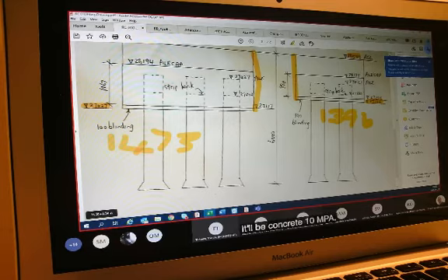One is blinding, and the other one would be my reinforced concrete. So it will be 10 MPa concrete, and whatever the size stone is that we will have, whether it be 19 millimeter stone or 13 or 25 millimeter stone, in blinding below my pile caps cast against my excavated surfaces.